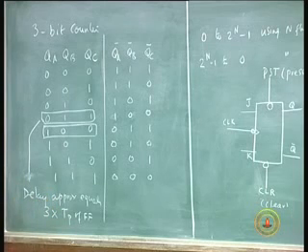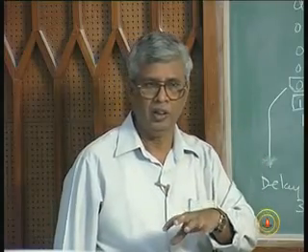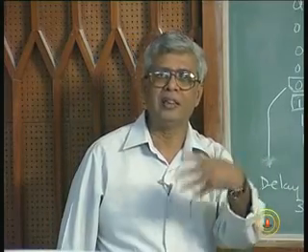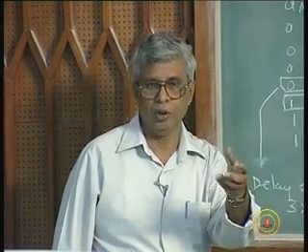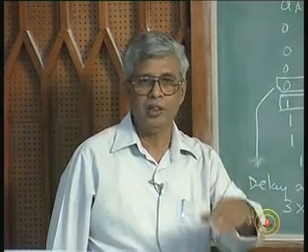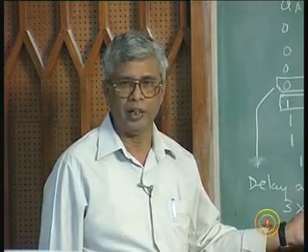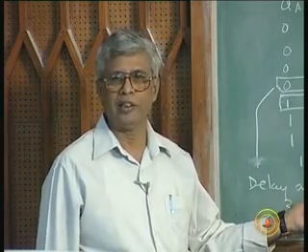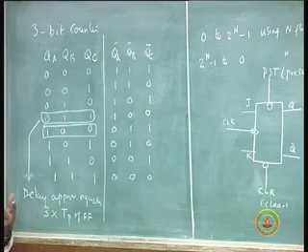Of course, there are other things like preset, clear, and all those. I am not taking that into account. See, once you have a number, you can always compute. But you should know there is a concept here. You should know there is a number you have to look for. Once the number is given to you, I can make it approximately 2 nanoseconds. But later on you find from the data sheet it's not 2 nanoseconds, it's 3 nanoseconds, that's all right. You have to do a computation. But you should know there is something like that we have to take into account.